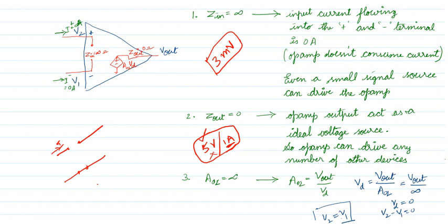So the inverter will be converting the DC to AC, right? If you are connecting more appliances, fan, fridge, AC, what will happen? You will see a voltage drop. You would have experienced that when you turn on your heater, the tube light in your hall blinks. When a bus driver starts the engine, the bulbs turn off for a moment and then on, because when you consume more current beyond this 1 ampere, your source cannot remain 5 volt.